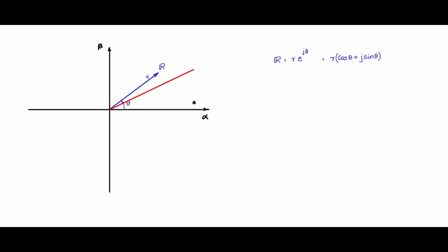another coordinate system, and I am calling that one the d axis and the q axis. D and q are orthogonal. This is another coordinate system having the same origin, only it is displaced from the alpha beta coordinate system by an angle rho. Now in this new dq coordinate system, how do we represent the same r in terms of the alpha beta representation?